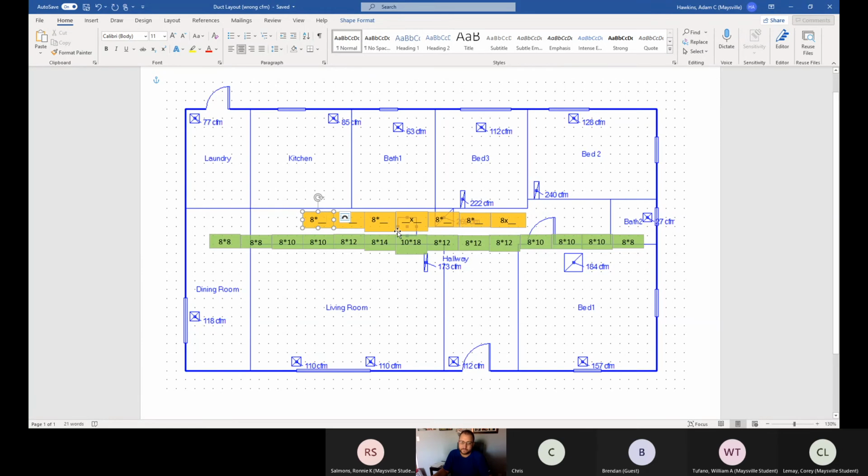See what I'm saying? Yeah, like my house. My house is that way too. My mechanical room's on the end of the house, and it's like a shotgun. You have to push it all the way to the other end of the house. So your ductwork has to be a lot bigger, and your static is a lot more because you have to push it farther.